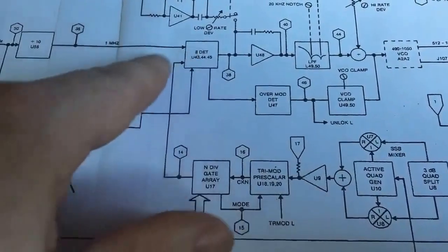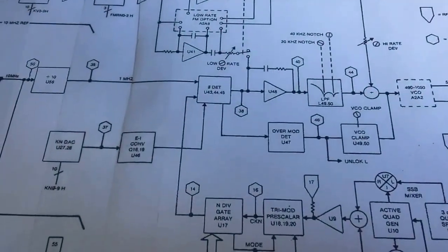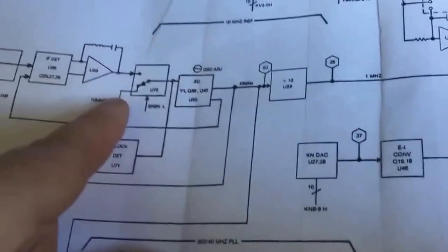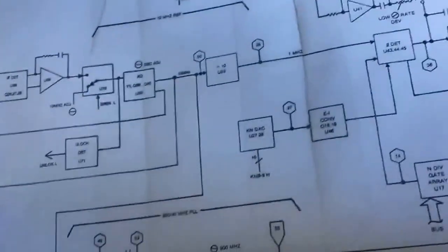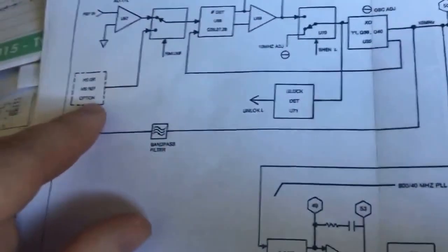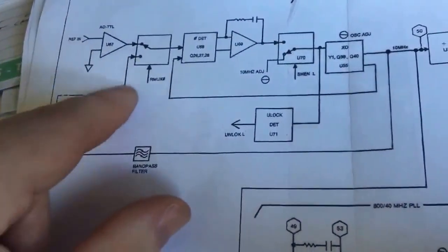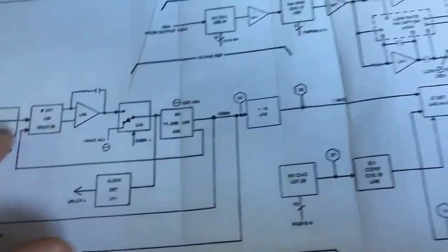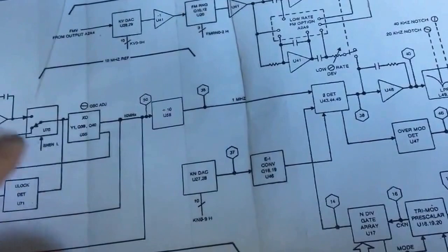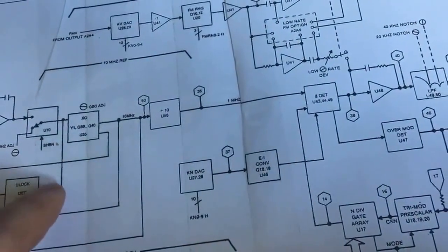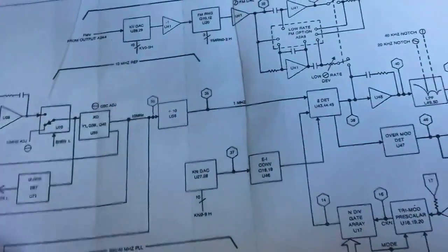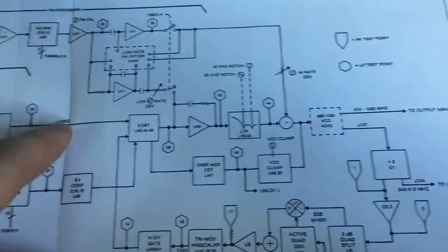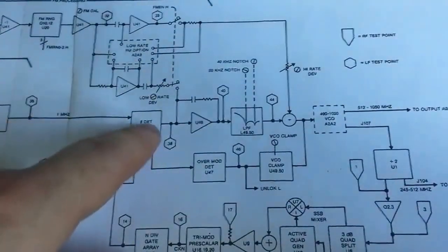I'm trying to figure this out. This is derived from the reference, if I remember rightly. There we go, over here. I've got the high stability reference in here, so it comes straight through, that switches over. If it detects the signal, it switches automatically. I've already confirmed that's correct. Comes through here, buffers and so on. All this is okay. I've already confirmed all that's right. It's one of the first things I fixed on this thing. Divide by 10 to get 1 megahertz. I know that's okay, so the phase detector signal on that side is perfect.